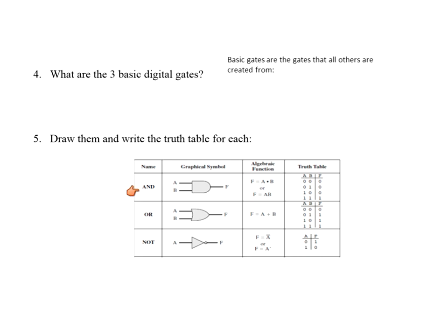The AND gate, you have to have both inputs high, or 5 volts each, to get a high out. Otherwise, you don't get anything out. That's why it's called an AND. You need this and that. The OR gate is a little bit different than the AND. The OR gate is, I can have this or that to get an output. And I can see that over here. So this or that or both to get an output.